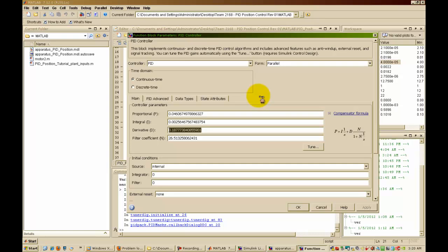Depending on what you got running on your robot, 10 Hertz is probably overkill, so you can probably slow that up a little bit and still get a very great response from your PID controller. Another useful fact is you probably only need to use a PID controller some of the time, not all the time. So put it in a block where you can turn it off when you're not in use, and that will save you a lot of processing power for other things.